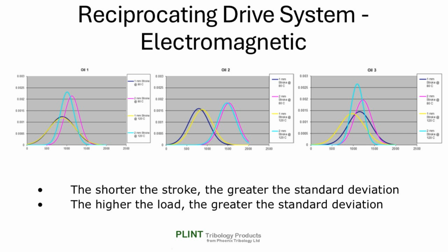This is indeed a system response, but it has more to do with the method of actuation than the fundamentals of the tribo contact. We are, in effect, using the tribo contact as a friction brake dynamometer to characterize the performance of the electromagnetic actuator.